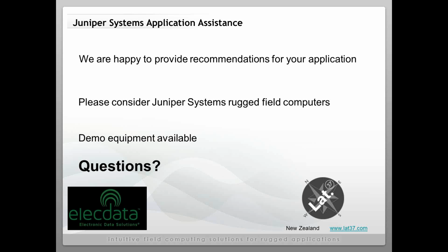You can just set up that field, and you align that field to the same communications port as COM1, essentially, from that serial port. And when that field is active within Data Plus, you push the read button on the reader, and then it will just automatically send it right into your field within Data Plus. That's one of the most handy features of Data Plus.